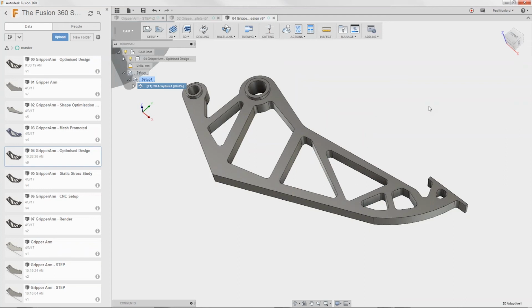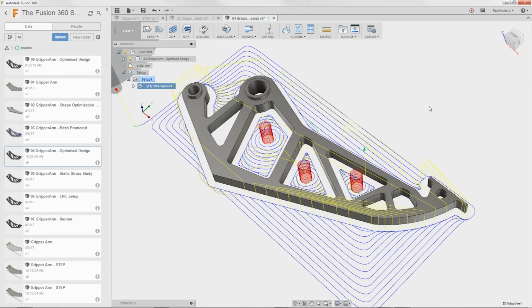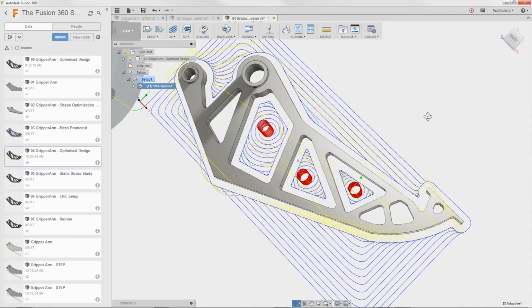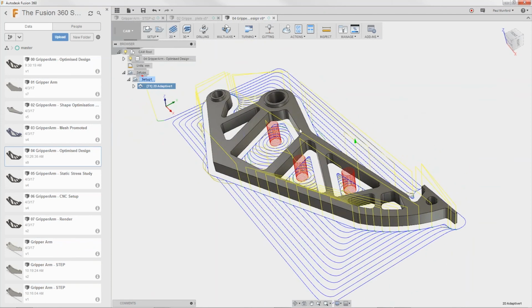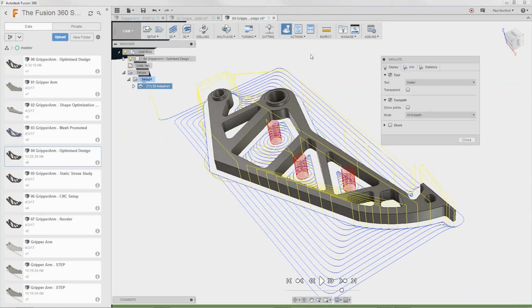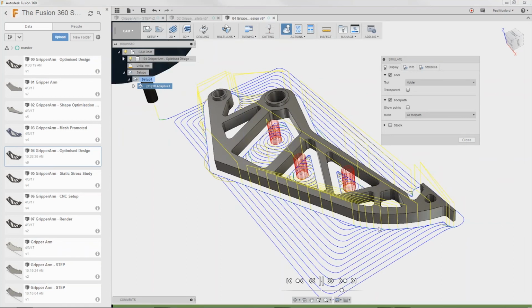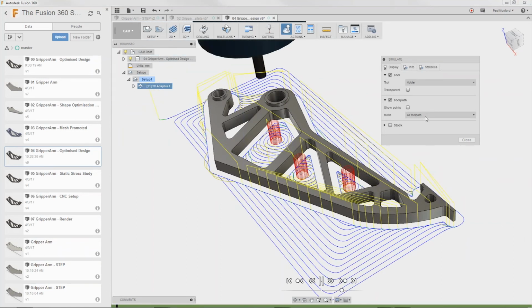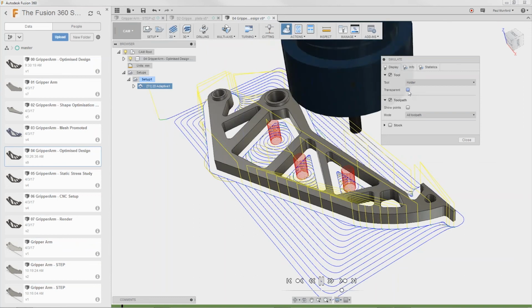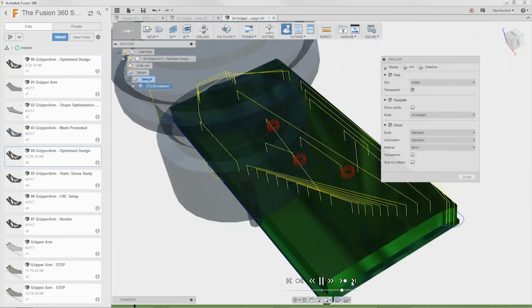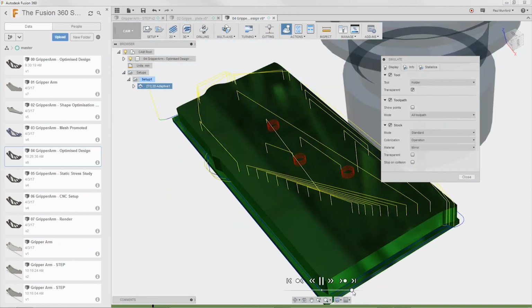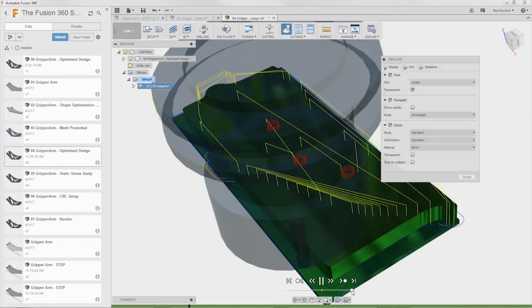and then I'm going to pick on the bottom profile here as my toolpath. By clicking on the bottom, Fusion already knows how tall the part is, so it's going to work out for me the best way to clear away all the material highlighted in blue. And maybe I'll just pick on some of these internal paths and we'll see how it gets on with that. So I'm going to pick OK. It may take a second just to get this simulation back.